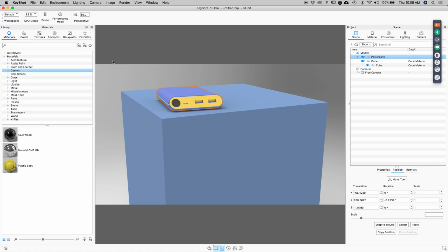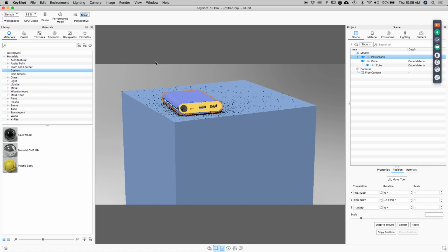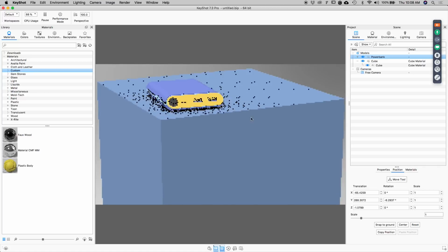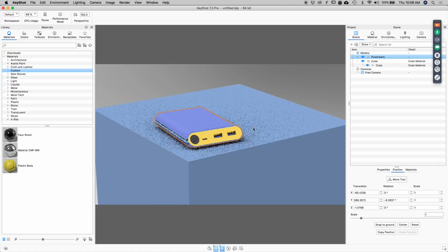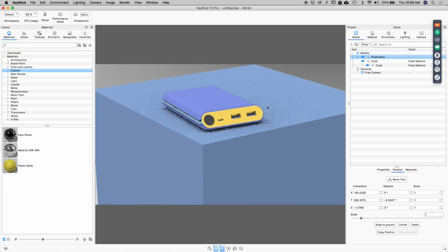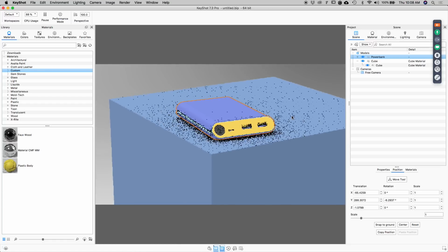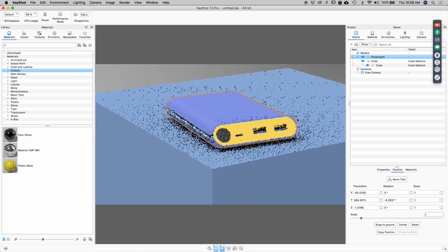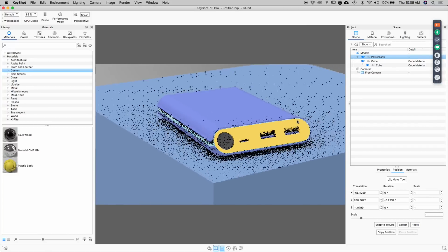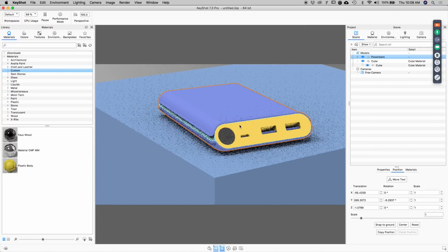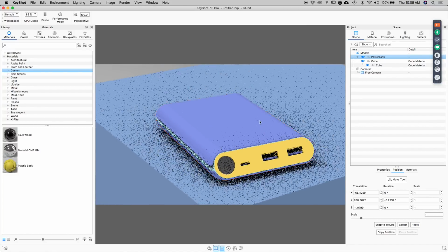So if I change this to 100, you'll notice this cube flattens out and the verticals get closer to being parallel. I would usually adjust that fairly early on, just because it allows me to compose my scene, get nice and close without getting far too much distortion on my object.